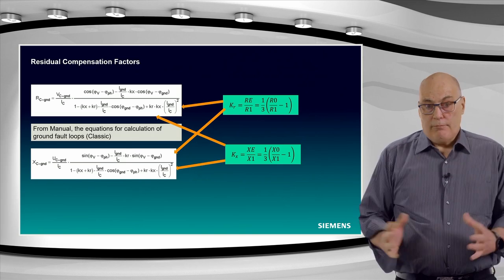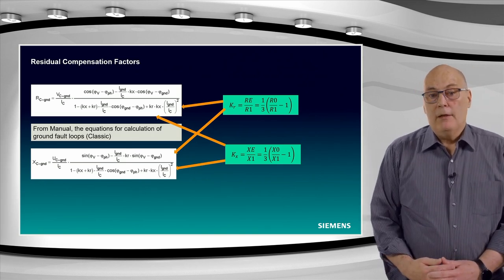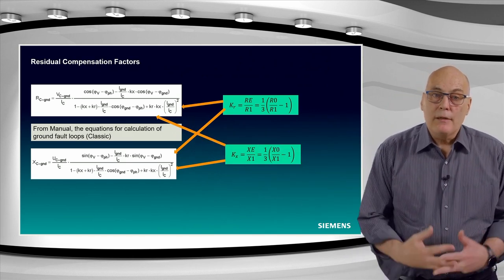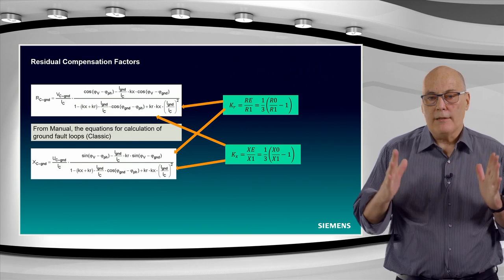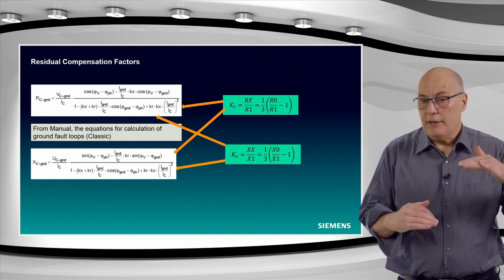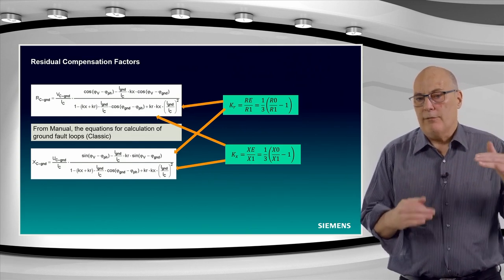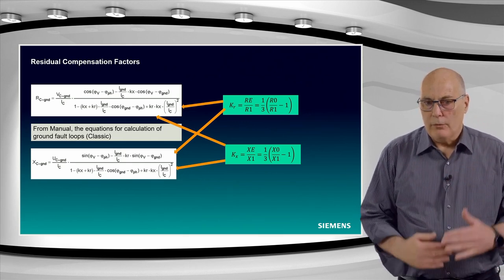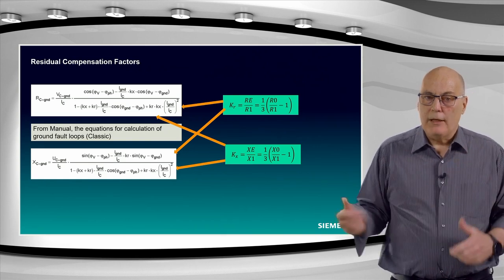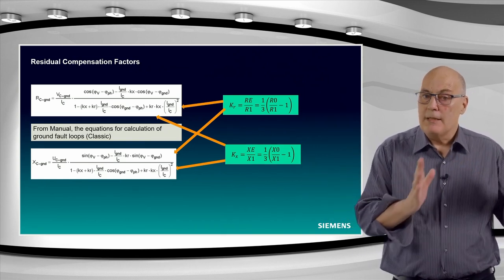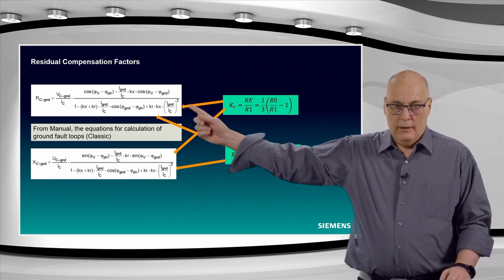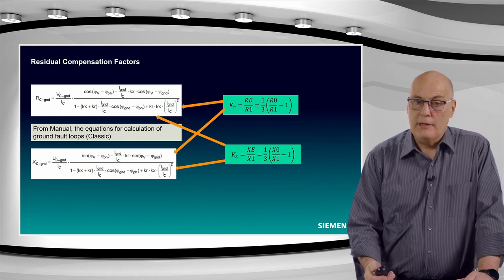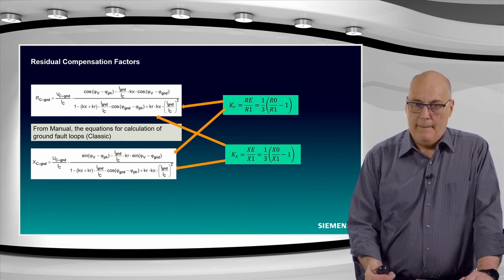Why do you use this rather intricate method? Because on the left-hand side of these two equations, the measured impedance is the positive sequence impedance. So we can apply the same reach setting. Well, later on we'll apply reach settings, and we then no longer discuss is it for a ground fault, is it for a phase-to-phase fault. It doesn't matter, because both the phase-to-phase faults and the phase-to-ground faults will measure an impedance which is basically the same. It is the positive sequence impedance, or as shown here, the loop impedance. And we can therefore apply the reach settings based on positive sequence impedance.